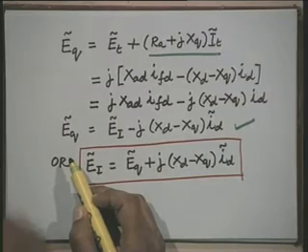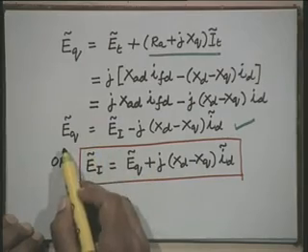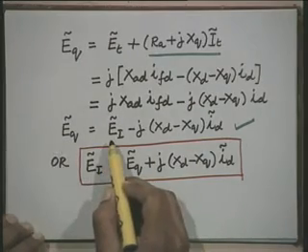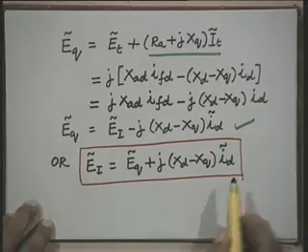Therefore, whenever we start drawing the phasor diagram, the first requirement is that we have to establish the location of d and q axis with respect to the terminal voltage. And now we have established a relationship between this E Q and E I. Now, this can be written in this final form.